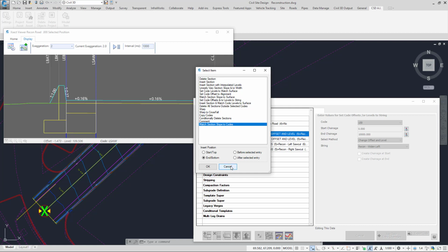What Project Assist is giving you is a string where you have the vertical design under your full control. Using a design variation will project the slope through from here to set the EB, but it will do it consistently over every section with no control. Whereas when you've got the vertical grading editor open for your EB, if you want to make the smallest change at any particular part of that design, you have the capacity to go in and make those changes yourself.